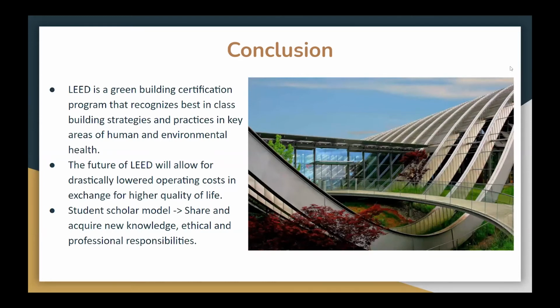We did consider other types such as concrete and wood, but we found that steel moment connections are very optimal during seismic situations using stationary moment frames. And steel would be ideal in many load and case factors. If we made the building out of wood, I believe it wouldn't handle as much dead load and live load given throughout the building. Though we use some parts of wood, just to reduce costs in terms of insulation and low emitting materials.